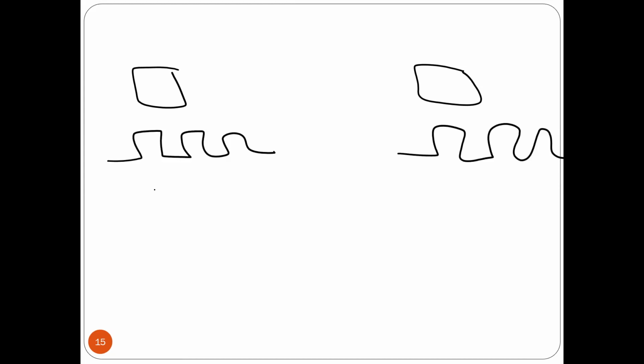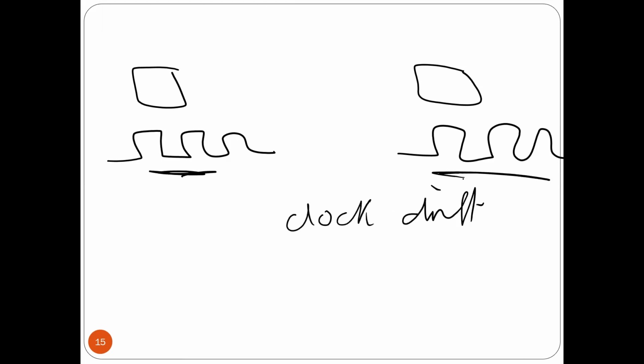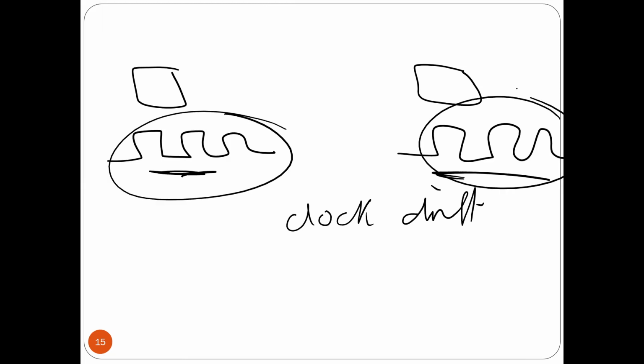So because of all of this, what happens is what we call clock drift. It's very difficult to generate exactly the same clock, so it's normal that we are not synchronized. You got what I'm saying? This is something normal. Okay. Even if we try to generate exactly the same signal, it's going to be too difficult to be exactly the same thing, because of many natural factors like temperature, like components. If you have a resistance, it's not going to be exactly the same value. There is a lot of variation in electronic devices. Okay. So again, conclusion, lack of synchronization is something normal, it can happen.